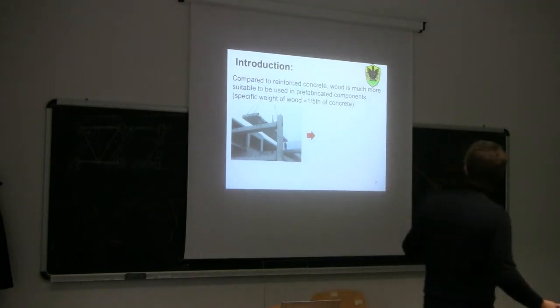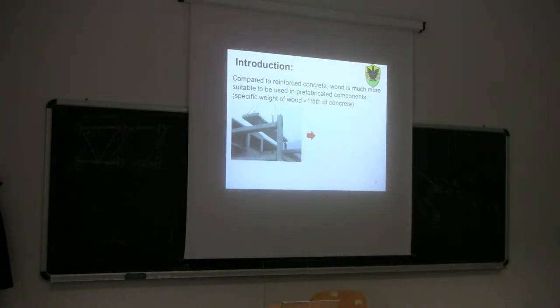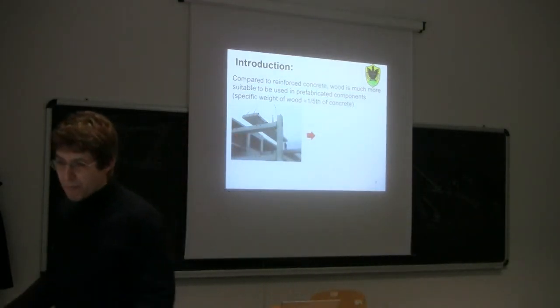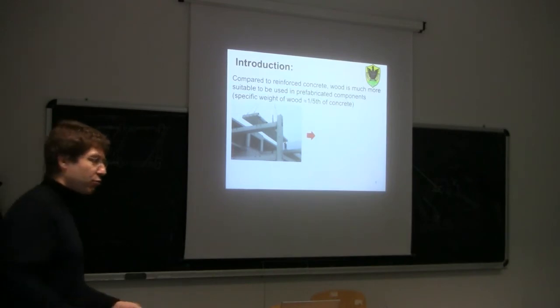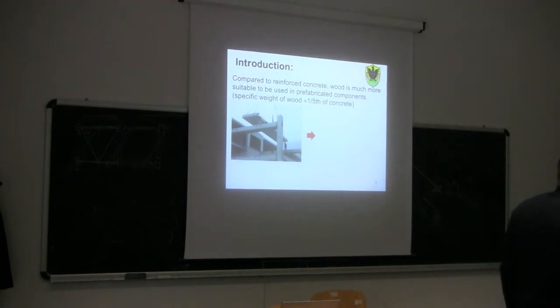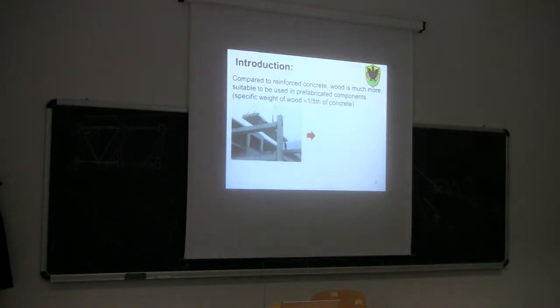Why is it not very common? Because reinforced concrete has an important problem compared to timber. If you remember well, reinforced concrete is much heavier than timber, which means that if you want to prefabricate, for example, the whole panel of a floor, you're going to have one member which is quite heavy to handle. So it's quite heavy to transport, quite heavy to lift, and then eventually to handle. For this reason, fully prefabricated solutions in reinforced concrete are not very common because of the weight.